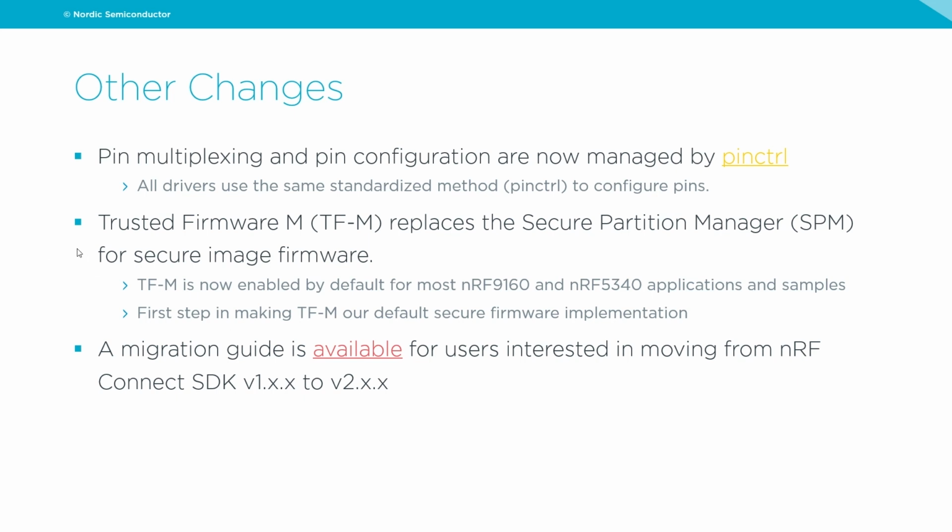And the next major change is that Trusted Firmware-M is now replacing the Secure Partition Manager for Secure Image Firmware. So TF-M is now enabled by default for most nRF9160 and nRF5340 applications and samples. And this is actually our first step in making TF-M our default secure firmware implementation. There's a great guide that talks about all of these changes, and it will really help you if you want to migrate your drivers or your application from the older nRF Connect version to the new versions.